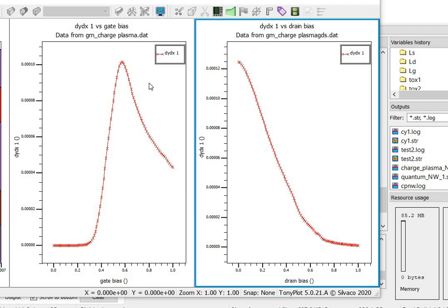My dear friend, this is the GM transconductance and this is the output conductance GDS. So we have found three different curves. First, drain current versus gate voltage. Second, transconductance GM versus gate voltage. And next one, output conductance with respect to drain voltage. By using these three curves, you can find out every AF and RF parameter. Let's go to the PPT.